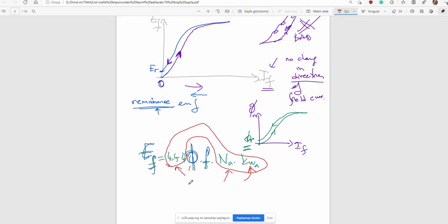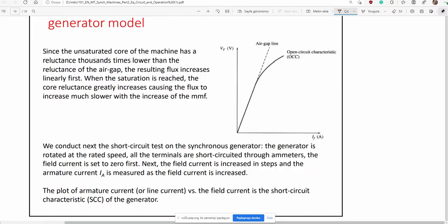But that parameter can be changed by field current, and that parameter can be changed by the speed of the rotor. But if you operate the machine on a constant frequency network, you remember the rotor speed is constant. It is at its synchronous value, 60 F over the number of poles, due to constant frequency. Now, that is the no load curve.